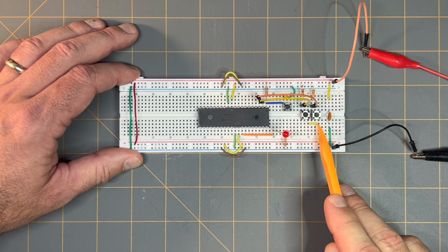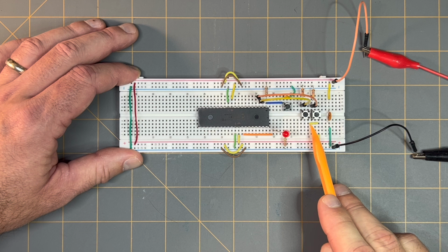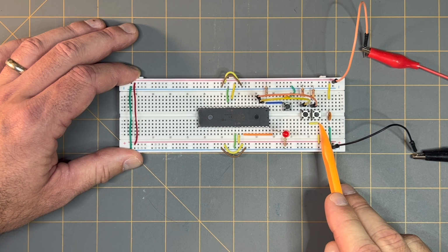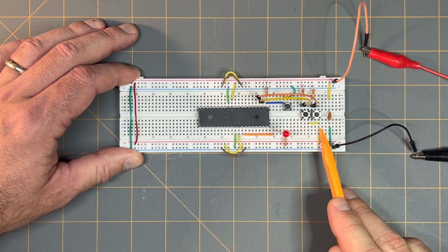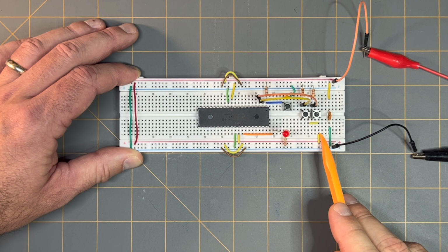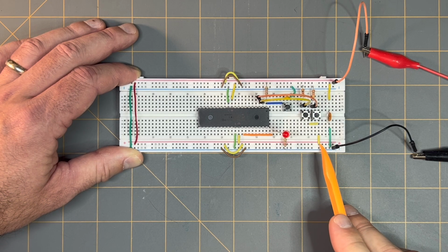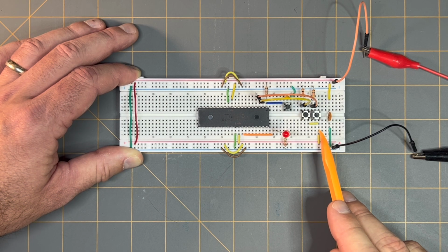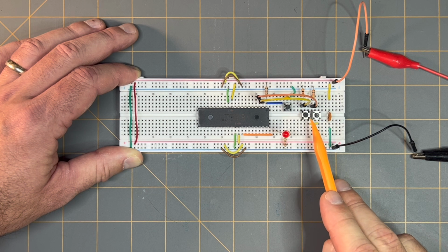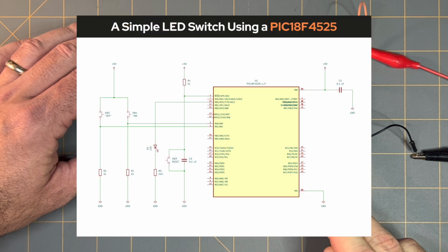And then continuing those two connections from both of those legs of switch 1 and 2 to the plus 5 volt supply, I've got this other yellow jumper wire where I have one of its legs at point J7 and the other leg of that jumper wire is in an adjacent point along this positive power rail here. So that makes the connection of the plus 5 volt supply going to both switch 2 and to switch 1, just like it is referenced on the schematic diagram.